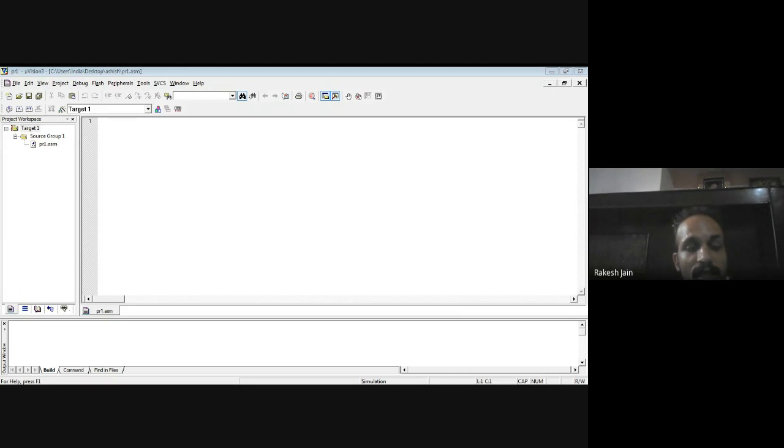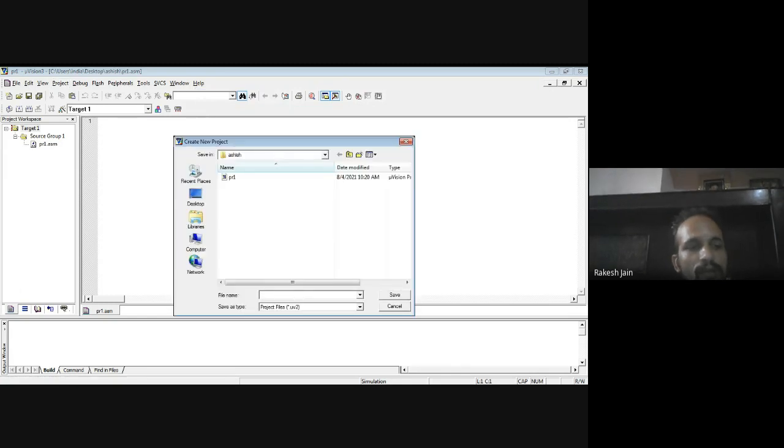Now what is the next step? See all the steps. Now go to Project, then New, and then New uVision Project. Then click on that.